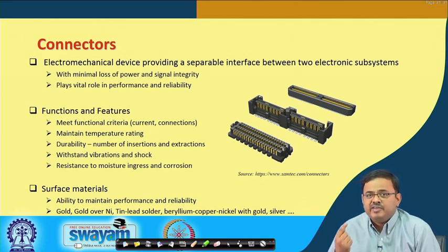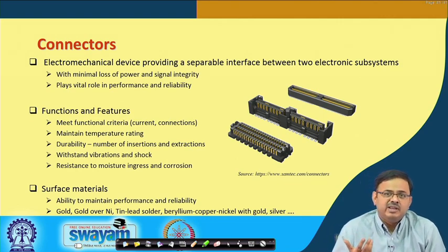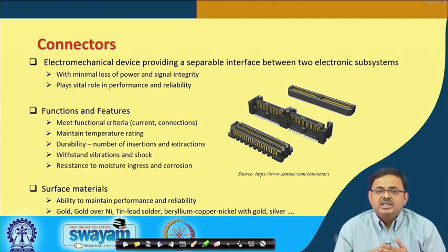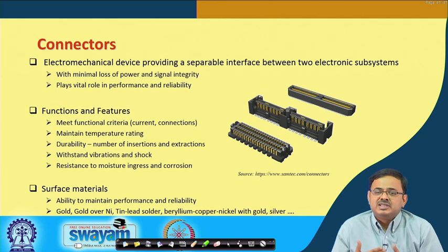This is one of the major causes of failure, or if not failure, degradation of the performance. Over time there is moisture ingress, and if there is moisture, the surfaces react, and there is corrosion that happens at these connector surfaces. So, all these actually degrade the performance.